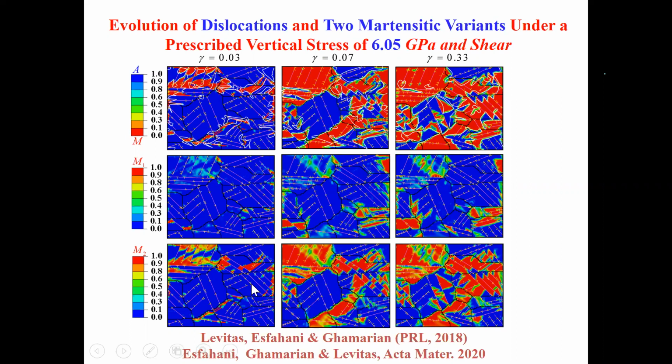And we combine this with plasticity, but we cannot combine this with traditional crystal plasticity because we still want to have our stress concentrator and dislocation pileups. And we introduce dislocation pileup through formulation of a contact problem of continuum mechanics. So we cut it here. In many places, we introduce the possibility of slip of one side with respect to another, like in contact of 2 bodies.